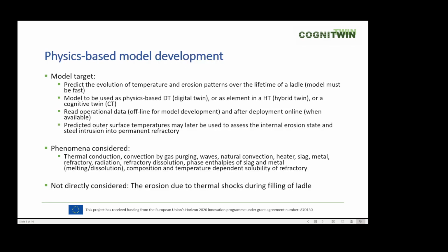So, a little bit about the physics-based model development. The target was to predict the evolution of temperature and erosion pattern over the lifetime of a ladle. That means that a ladle is used multiple times, and we have to accumulate the data from time to time and simulate the behavior of the refractory and the temperature through the life of a ladle.